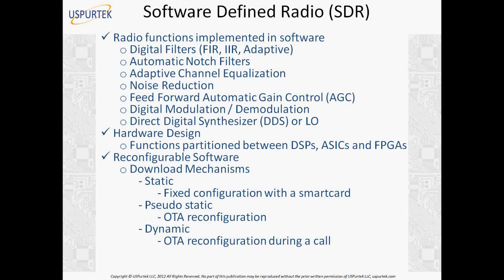Okay, so now let's see how we classify different types. This slide shows the progression in the advancement of SDR, software-defined radio. At level 0, you have a conventional implementation in hardware. This is like your conventional AM or FM radio in your car. That is level 0. So we call it level 0 SDR, no software actually.